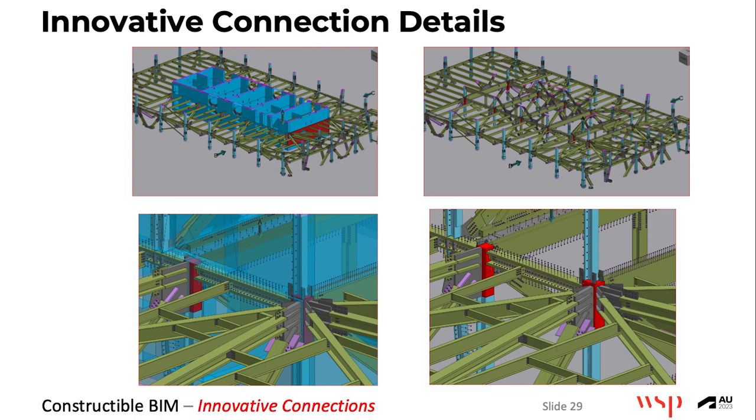That's a shop weld, and then the field weld's out here, and if it's not a field weld, it will be bolted, but there's a temporary bolted connection here. But this is a field weld, but this, let's call it a gusset, converts the flange forces into web forces.